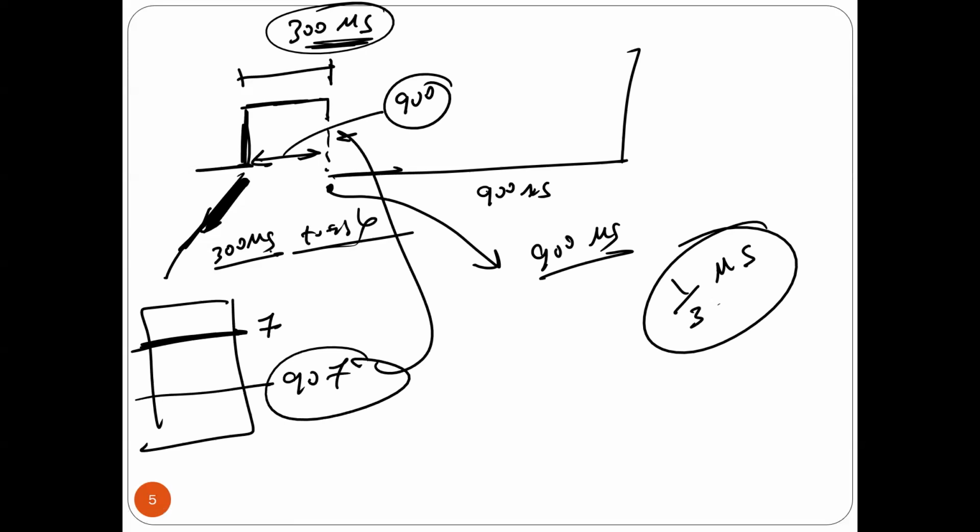So number 1, here I have to convert the time to number of counts, because the counter is counting. Currently it's number 7, so please, after 900 counts, please toggle. Why 900? Because 900 is equivalent to 300 microseconds. Again, I'm going to give you the details next time, but I just want you to understand how I'm going to link this counter to the input capture or output compare, because everything is relevant to the number of counts.